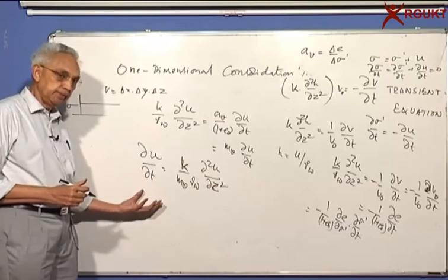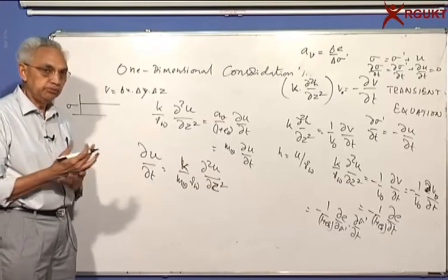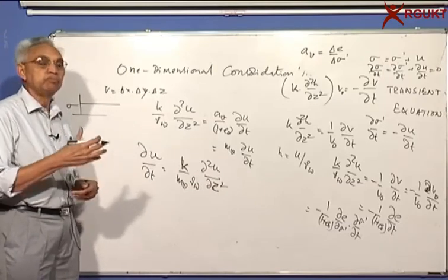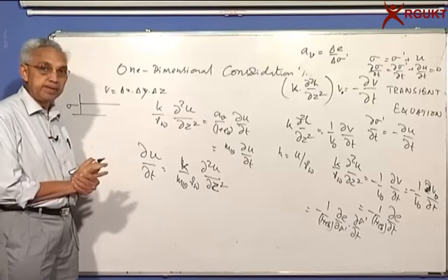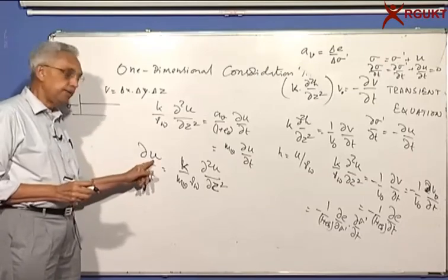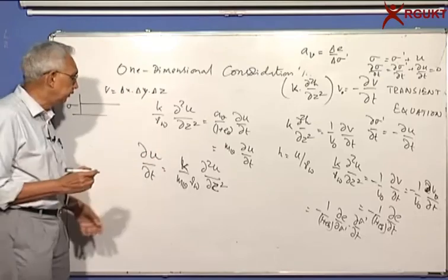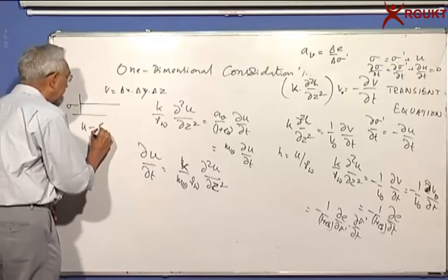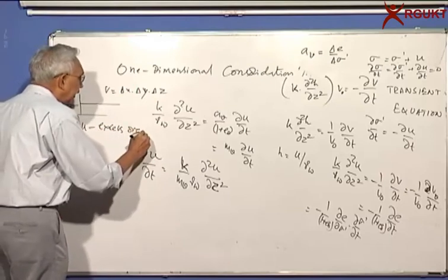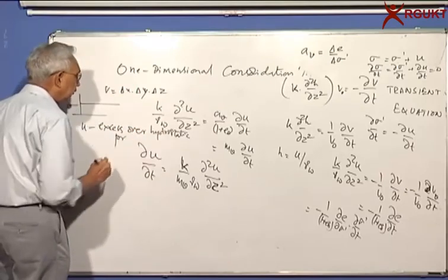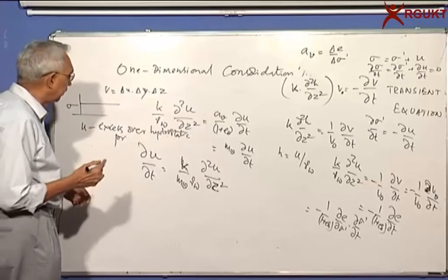Whatever is happening in consolidation is also true for conduction of heat in solids, electricity in conducting medium, etc. The derivative of u, the pore pressure, is due to the applied loading. So usually u is called excess over hydrostatic pressure. So usually we say excess pore pressure.